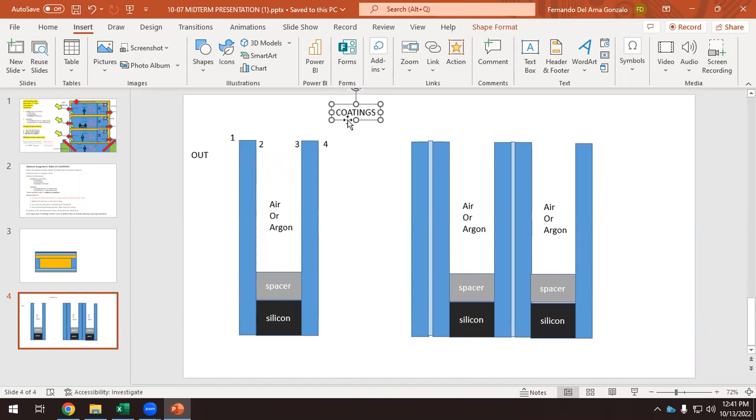It's a very thin layer of usually something made of some metals, chrome, or very heavy metals, but so thin that you can't notice. They are almost transparent. And then we can apply this coating on layer 1, 2, 3, or 4. If we apply this on layer 1, this is out, and this is the indoor environment. Usually we have to specify: I want this coating on layer 2. Then they apply this on layer 2, or on layer 4, or layer 1.